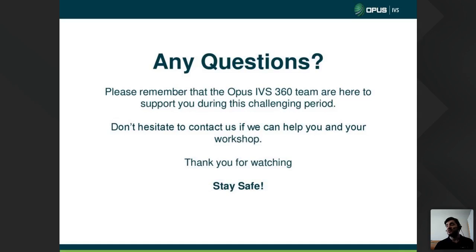John Rich has asked if we're able to program keys on Ford. At the moment, it's a no. For the FDRS team, they would require a security accreditation, but because this is a remote function, we're not comfortable doing key codings yet because we don't really know the vehicle. We haven't got the vehicle in hand. So for safety and security purposes, the key programming or any feature that requires security accreditation is on hold. So we don't know if that's something we're going to bring forward or look into in the future.